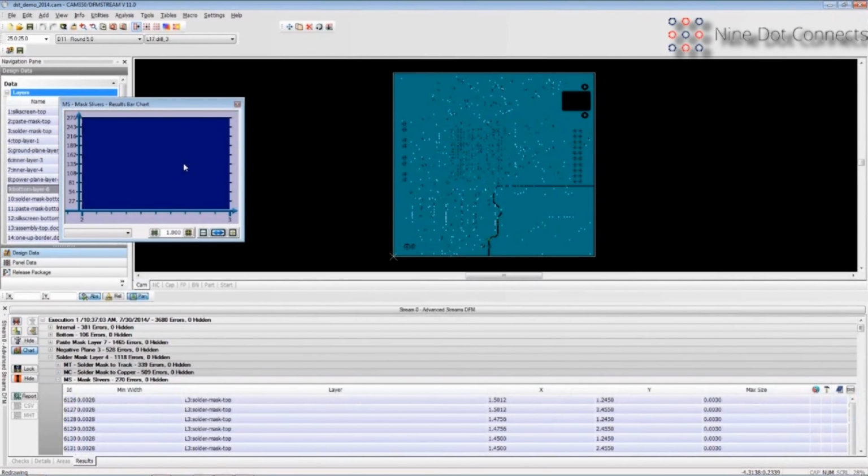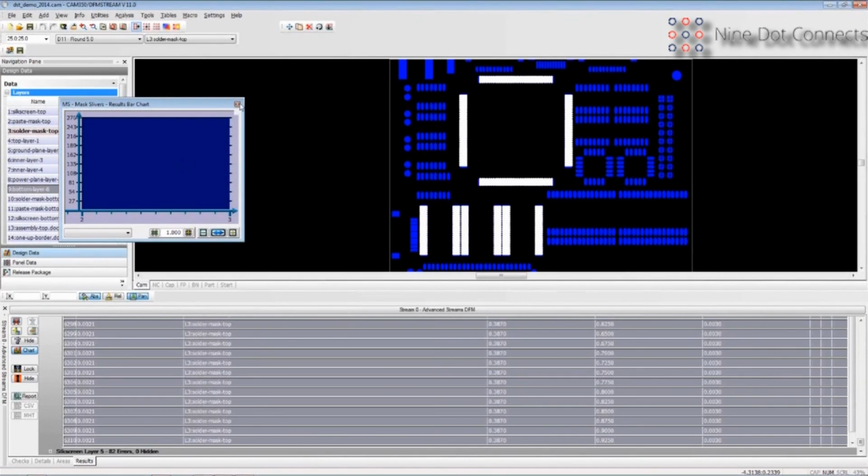So again, if I really need those dams, I have to first of all find a fabricator that can hold whatever that number is. 2.1, that's going to be a stretch, I think. But second of all, I might just say, go ahead and make these into, we call it a window pane or a block clearance or something like that. Again, if I can say that up front, less back and forth between me and the fabricator.